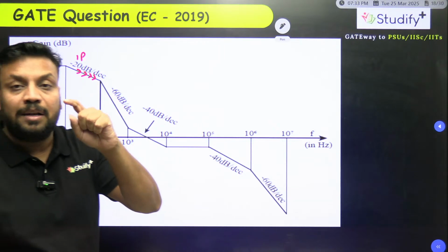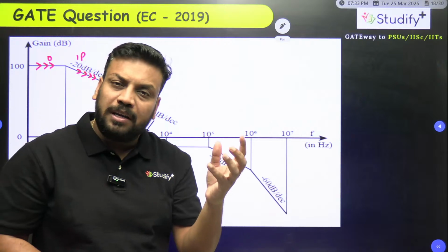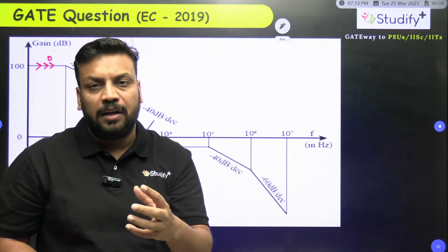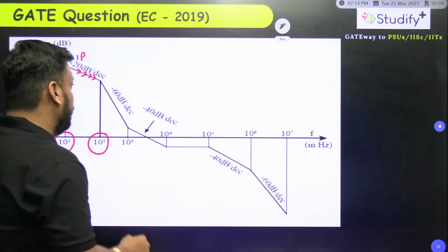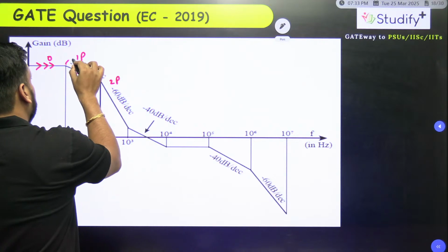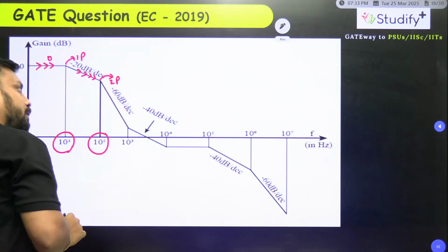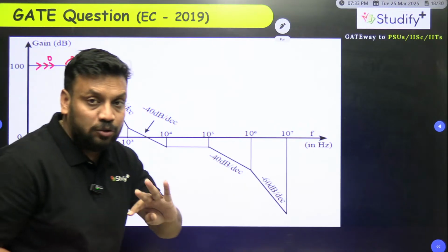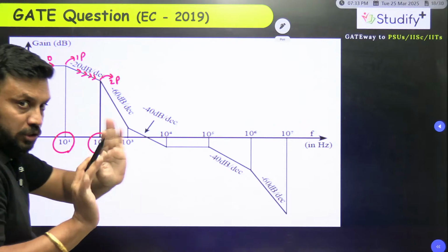What I need to add in -20 so that it will become -60? Add -40, sir. So -40 means 2 more poles are added. So here will contribute about 2 poles. So at this corner frequency 1 pole contributed, at this corner frequency 2 poles contributed. As of now we are having total 3 poles. Okay, 1 pole here, 2 poles here, no zero as of now.